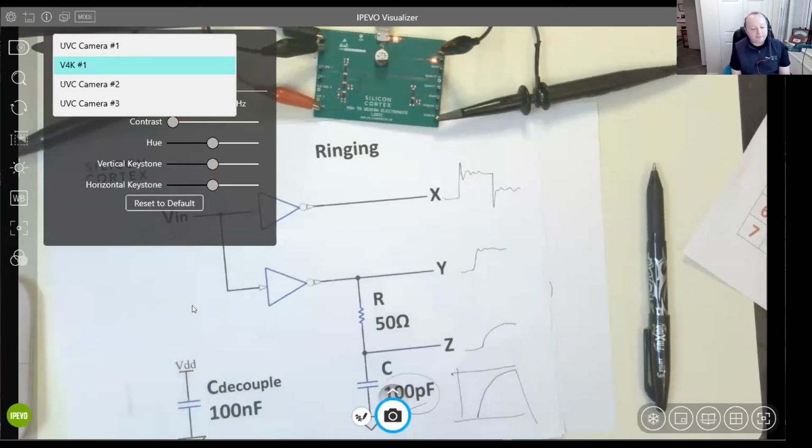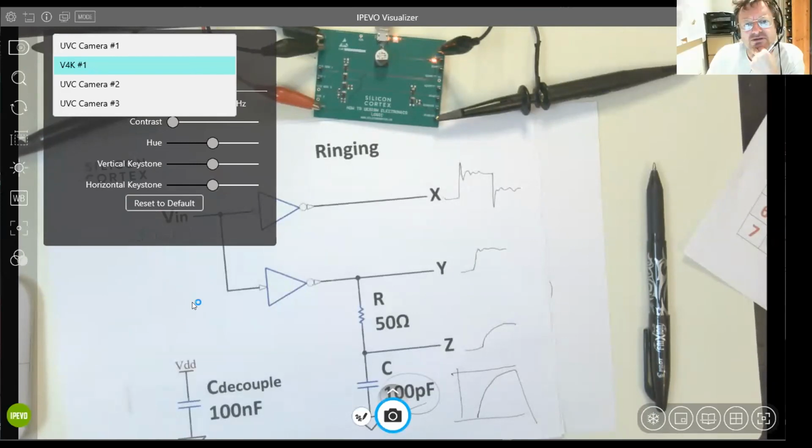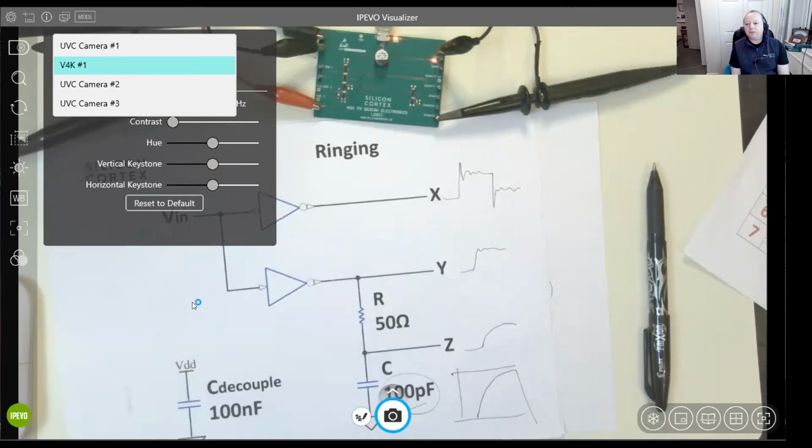Yeah, so the way we fixed it in the end was we had to put the chip on its own I2C port. Now, fortunately, because we're using the ARM Cortex M4, it had a number of I2C ports. So completely destroying the notion of it being a bus. You sort of isolated it and put it on its own. Absolutely, I had no choice to make this thing work. I'm sorry to say, Maxim have a very good reputation. You know, engineers love their chips to death.